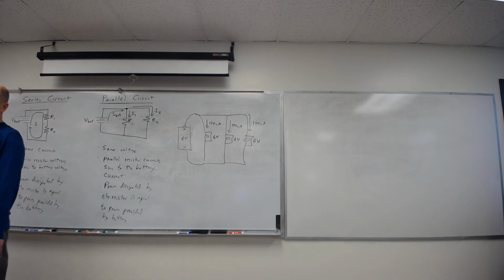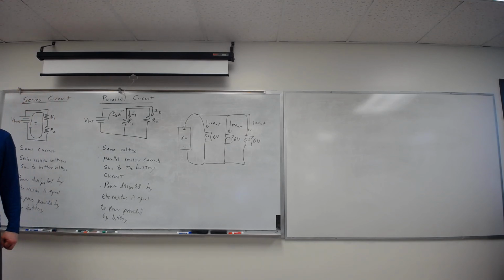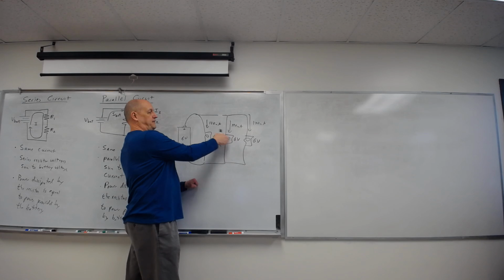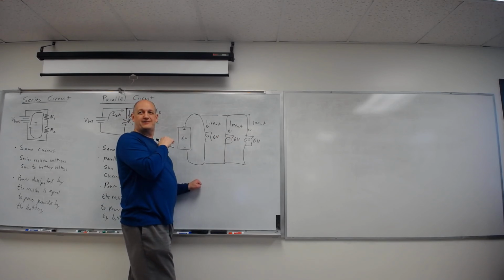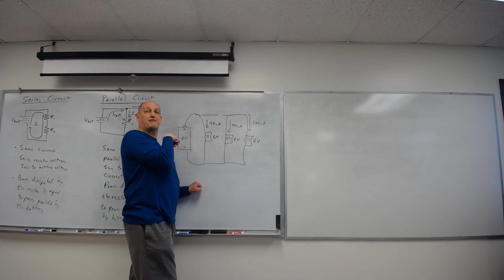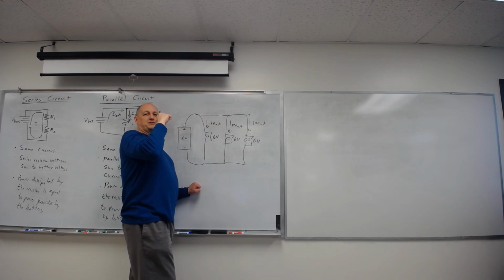And that's the most common error on that one, by the way. So if you measured it wrong, that's fine. That's the toughest thing to measure. You have to make sure you're measuring the current only through that one. A lot of you would disconnect here, measure it, and call it that battery current, because when you hook it back up, it provides both those. So if you got like a 240 somewhere, that means you probably disconnected 2, and we're actually measuring the current through both.